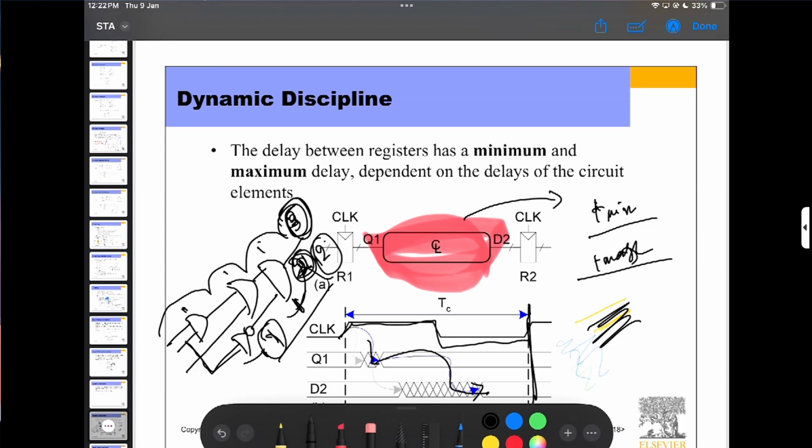So after 2 nanosecond, if we take 2 nanosecond as the minimum, then this circuit will change after some time, like after 1 nanosecond it will change. So at the position of 3 nanosecond, if we start the circuit from 0, then at 3 nanosecond the circuit might have changed. We don't want that in our input, so we take the maximum delay, that is 3.